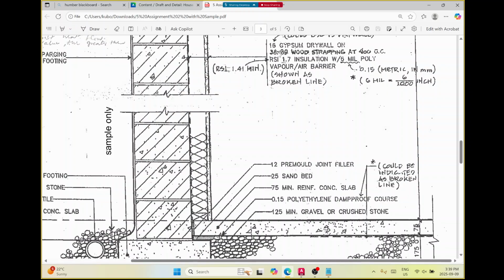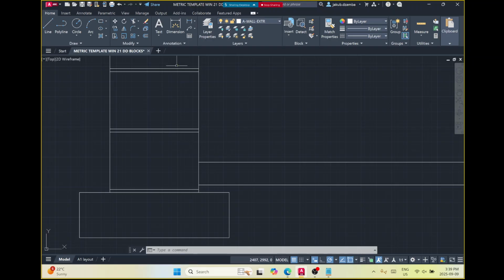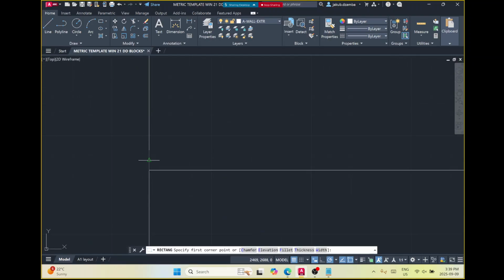So that being said, we're going to draw this rectangle at the bottom here. We've already had the tools to do it. We've already done it before. So let's grab a rectangle, click in that corner. Careful that you don't get the triangle. That means you're snapping to the middle. Go right to the corner and go at 38, sorry, I messed up. Let's try it again.